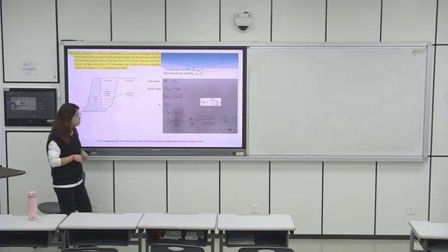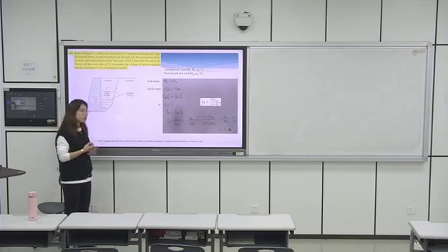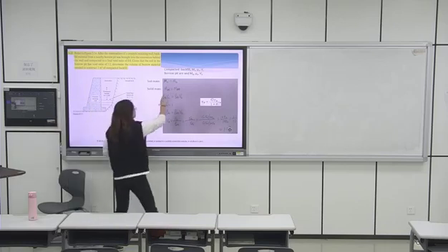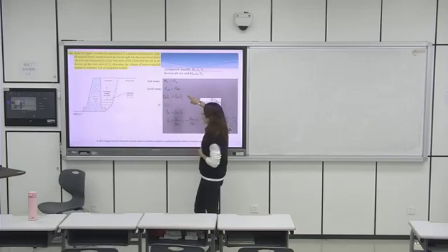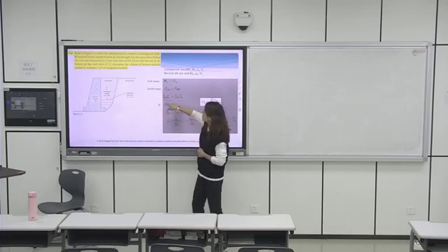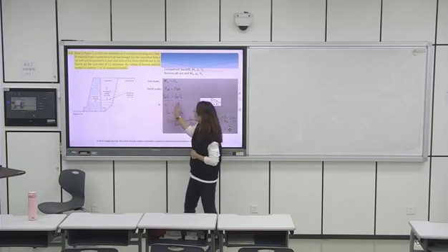So actually you need to get an equation, and the equation is that the mass is the same. The mass is the same, water content is the same, the solid part is the same. The different thing is just the void ratio. So if the mass is the same, that is, the solids are the same, then we can go to this, right? This is the dry density on that side, the dry density on this side, and the volume on that side, the volume on this side.